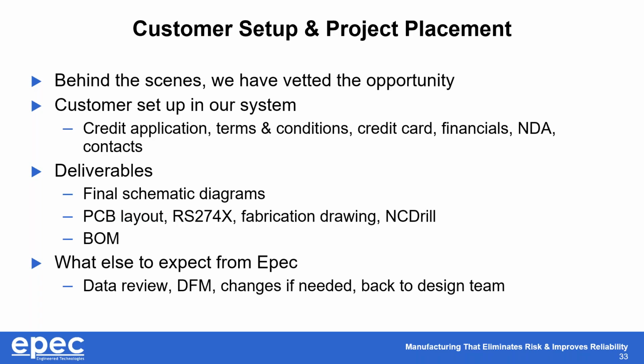We've set them up in our system. We've done credit applications, terms, credit card, financials, NDAs are in place. We'll work with our customers to set all of that up, and then we'll have our deliverables laid out. So after final schematic diagrams are done, the PCB layout, RS-274X formatting for Gerber files, fabrication drawings, NC drill, and even a finalized BOM if something was changed in between.